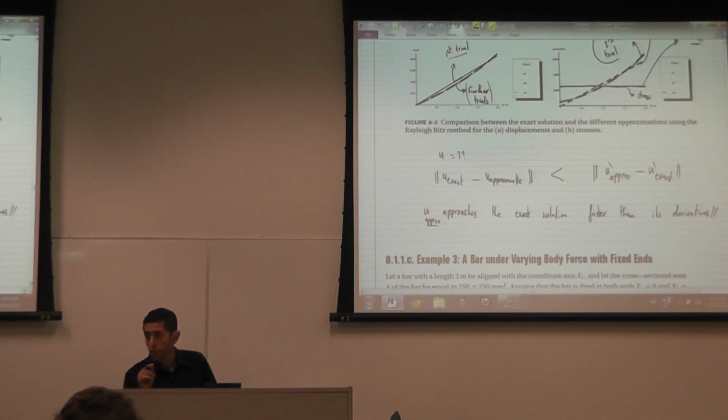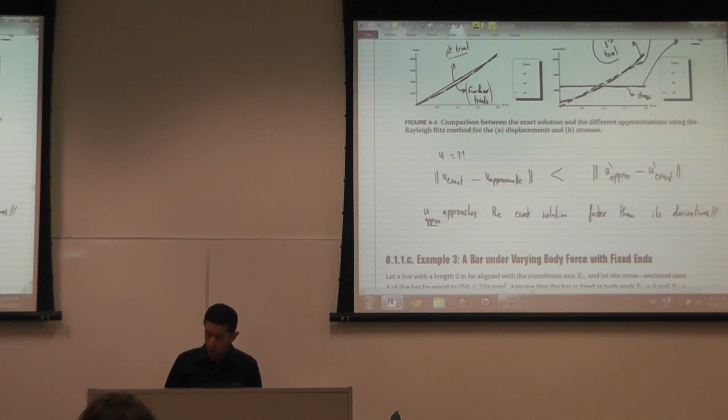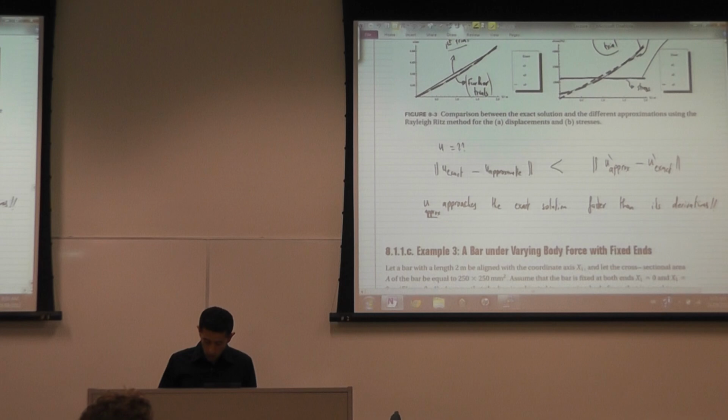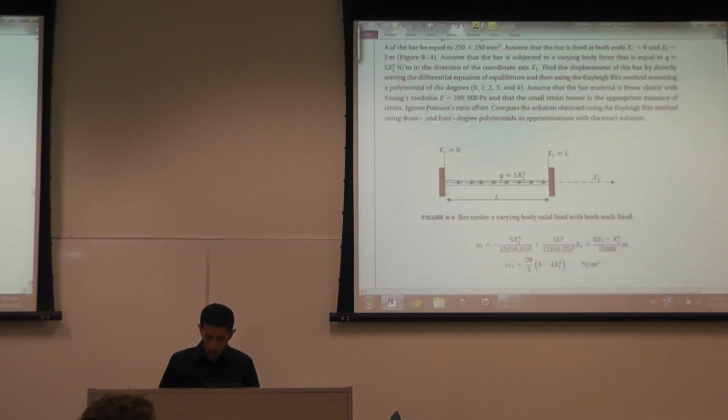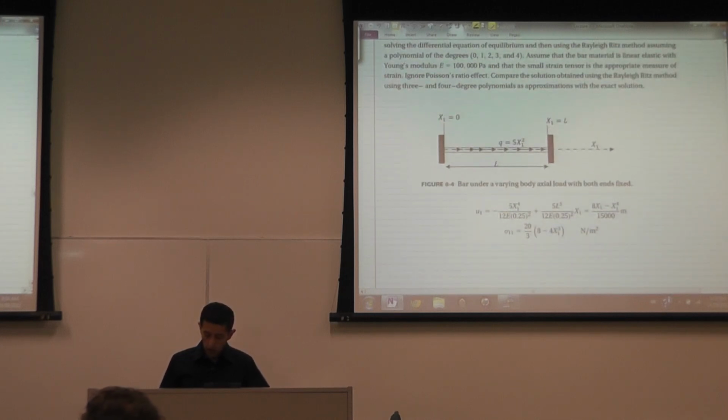If you actually go into Abaqus, I'm not sure about how ANSYS does it, but if you go into Abaqus and you change the slider of the smoothness, you can see how the stresses are very discontinuous. And we'll see it when we actually start using the software. Another example, so you can look at the solution to this example.